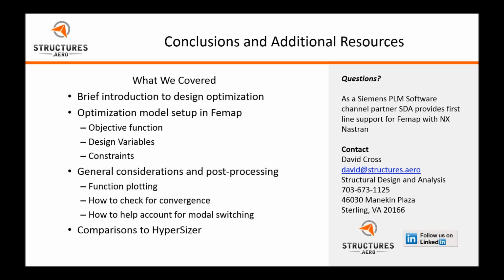Solution 200 does have the capability to define equations to several different responses. You can pull responses not from the property but from the element and then write equations. So you can definitely customize things like that. FEMAP doesn't support it, but there should be enough documentation in the user's manual to get you started there.